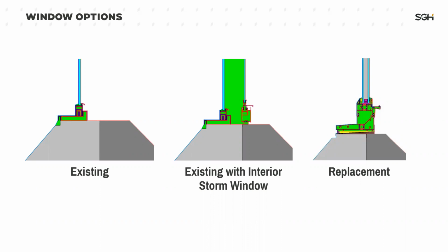You can see this is a much more modern looking window sill detail. We have an insulating glass unit, which is 2 panes of glass here with an air space in between. And you'll also notice that this one looks a lot bulkier. If you're standing on the outside here, you'll see this distance, which is called the sight line, from the base of the glass until the base of the rough opening, is a lot taller. It's a lot thicker frame than the existing windows. So it would be a pretty drastic change to the aesthetics of the building.